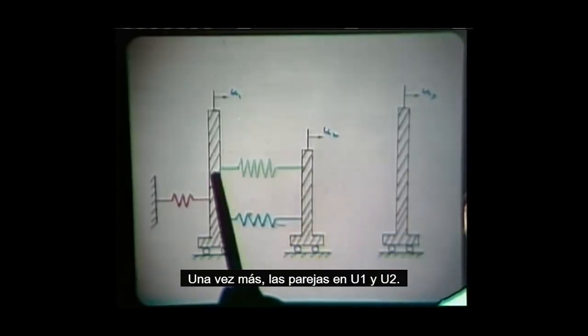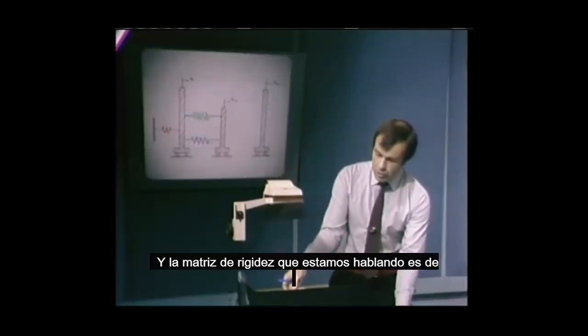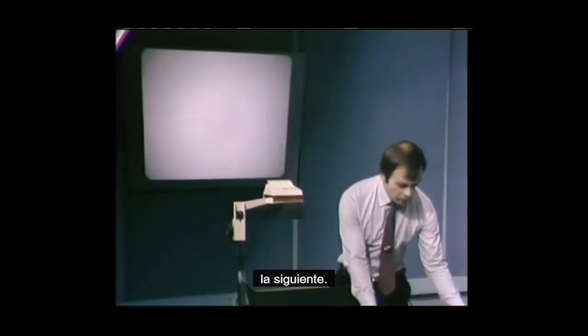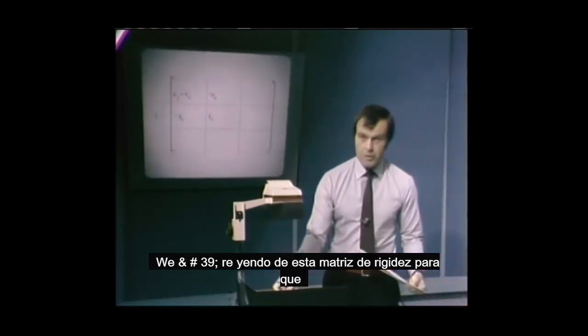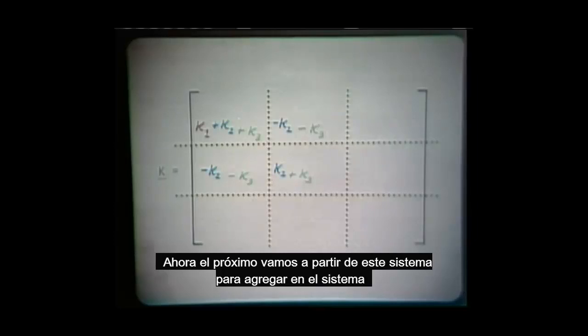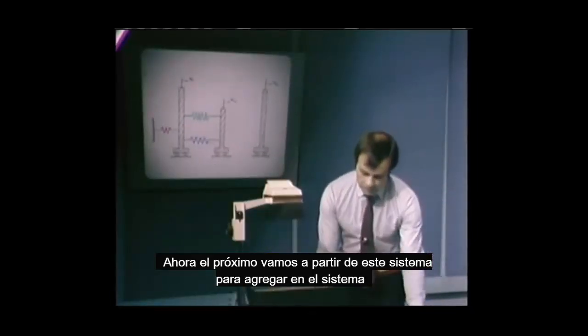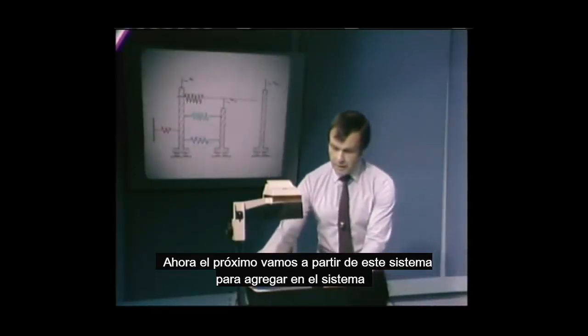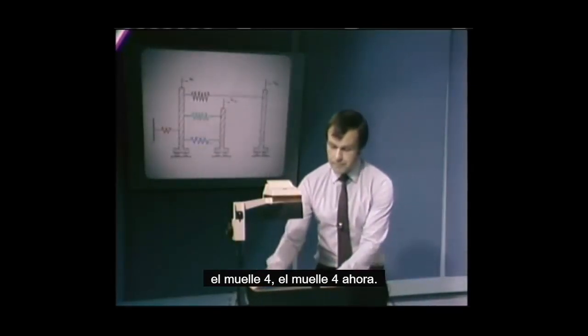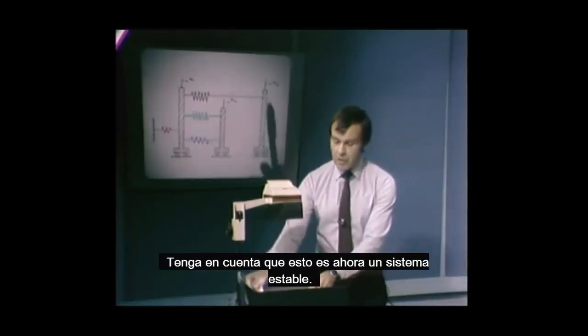Again, it couples into U1 and U2, and the stiffness matrix that we are now talking about is the following. We are going from this stiffness matrix to that stiffness matrix here, adding the green K3 in there. Now, next then, we go from this system to add into the system the spring 4. Spring 4 now. And notice now, please notice that this is now a stable system.